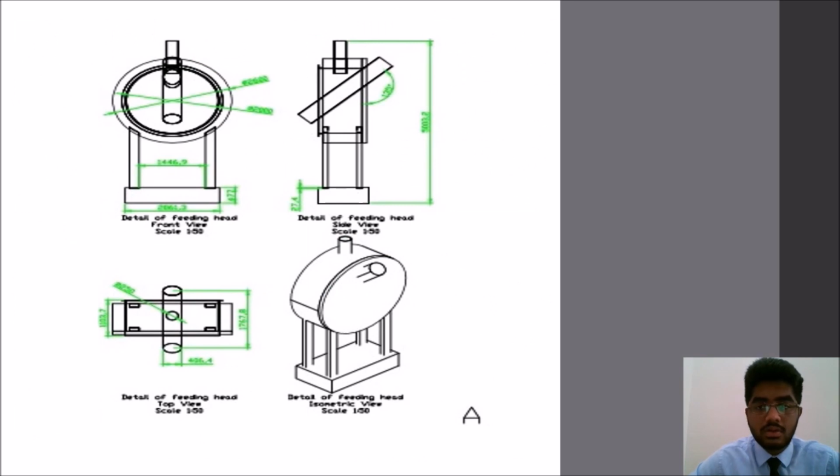This will be our raw material feed, which can also be called the feed chute. The feed pipe slope is greater than the natural inclination of the material, so the material can flow into the rotary dryer smoothly. This will be our exhaust outlet, where it removes off-gas and small particulates.